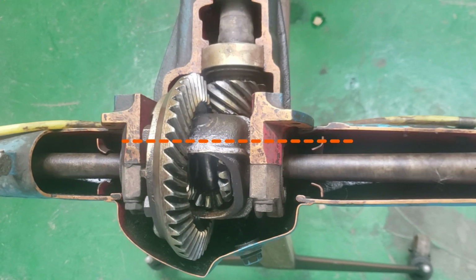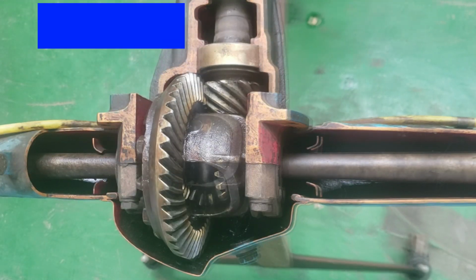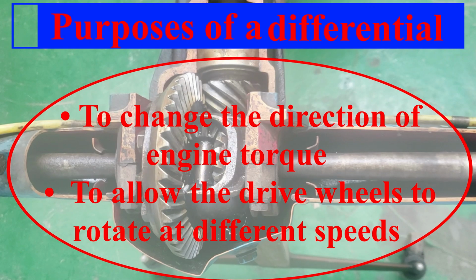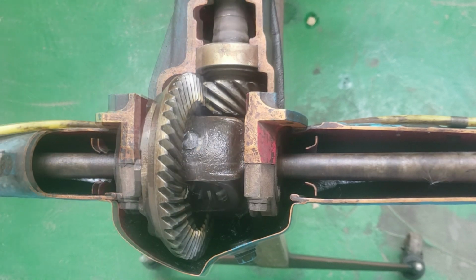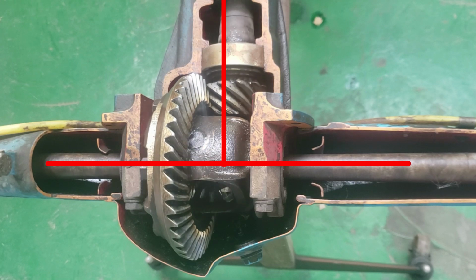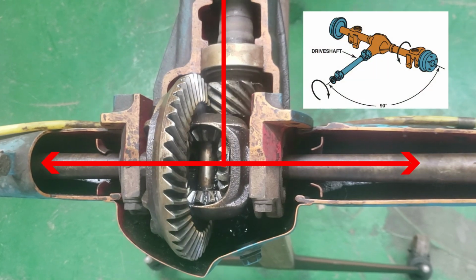The differential allows engine torque to be applied to both drive axles, which rotate at varying speeds during cornering and while traveling over bumps and dips in the road. The differential also changes the direction of engine torque 90 degrees from the rotation of the driveshaft lengthwise with the vehicle.